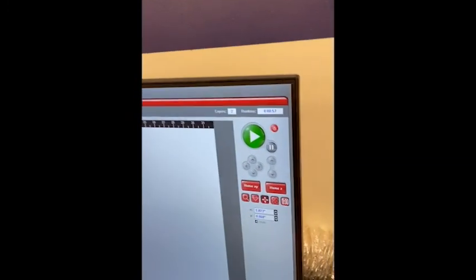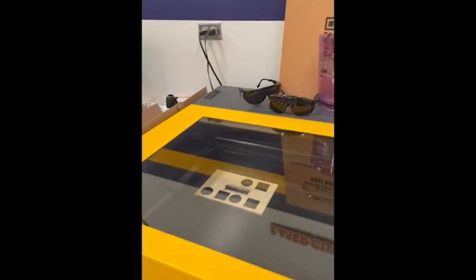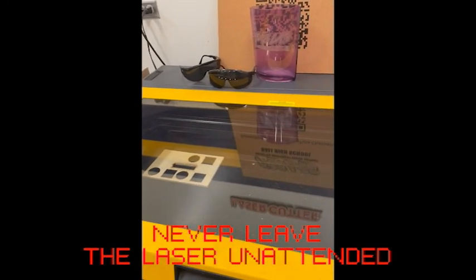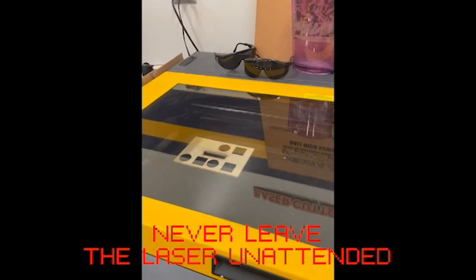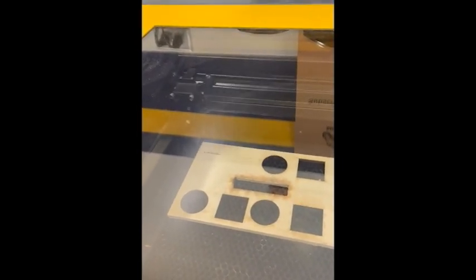I can either press the green button here to start it, or I can click over here on the green button. The important thing is you don't want to ever walk away from the laser cutter for any reason. You want to keep an eye on it. So I'm going to stay right here, and I'm going to hit play, and it's going to lower or raise the bed according to what the measurement is. The laser cutter head will move into position. It's going to do the black first, and then it'll do the cut. So we'll check back in a second.